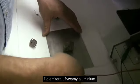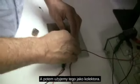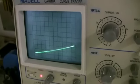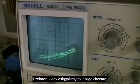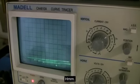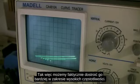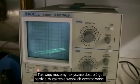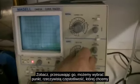And you can see with the rock, we use the aluminum for the emitter, and then we'll just use this for the collector. We use a piece of wire for the base. So you notice right away we have a junction. And see, when we get this where we want it, then we get a transistor. More in the high frequency end here. See?